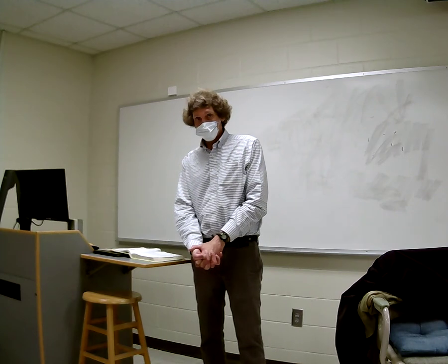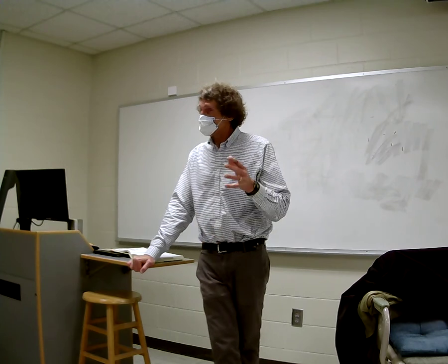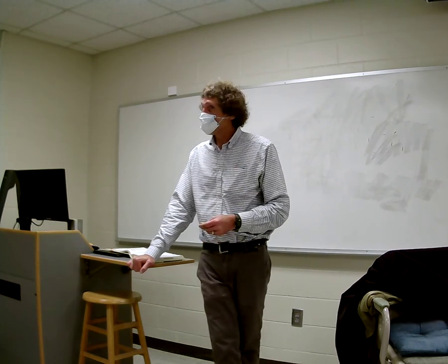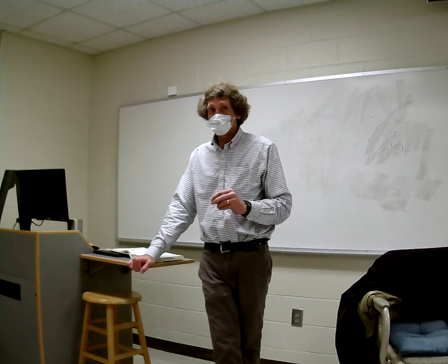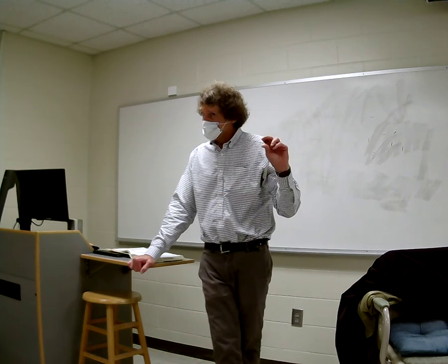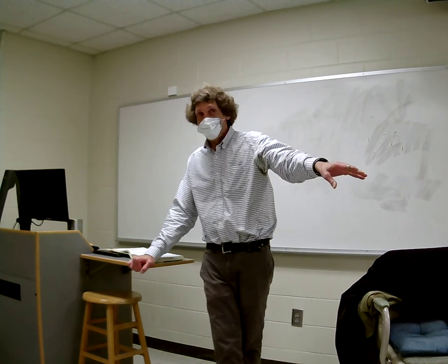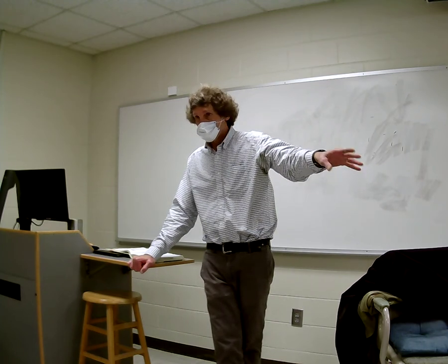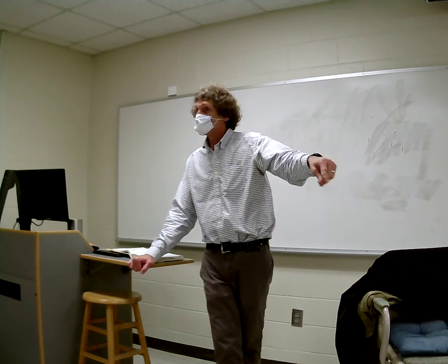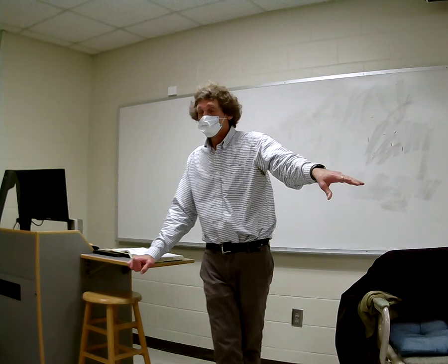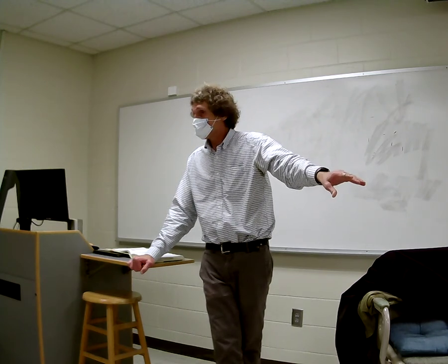Either one's useful. So what we do in the United States to try to minimize that, especially at hospitals and around airports, is we have rules called FCC guidelines, and they limit the amount of power transmitted in airwaves, as well as the amount of power that can be placed into the walls over certain frequency domains. It's called conducted emissions. That wall outlet is 60 hertz, basically at 117 volts RMS, right?